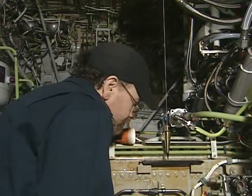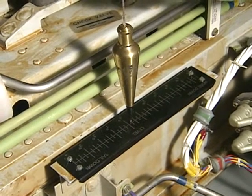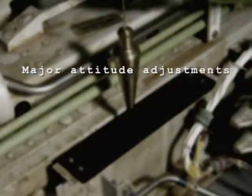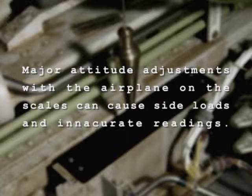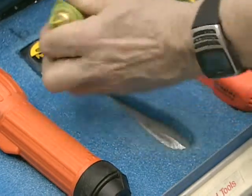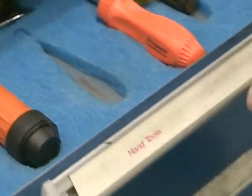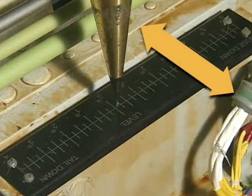You won't need to level the airplane exactly until after it is moved onto the scales, but you want to get it close now because major attitude adjustments with the airplane on the scales can cause side loads that can lead to inaccurate readings. Note that a plumb bob is not included with the airplane, nor in the BEW. You will need to supply your own. Make sure to remove it when the weighing is complete. And although it is not required, for best results, we recommend also leveling the airplane laterally.